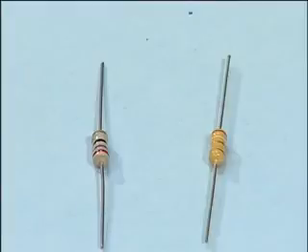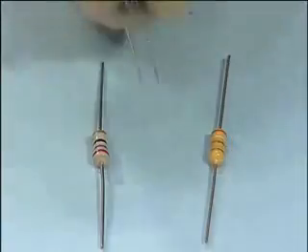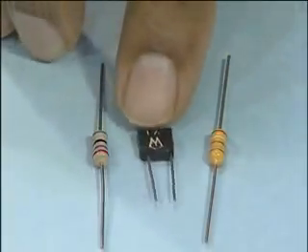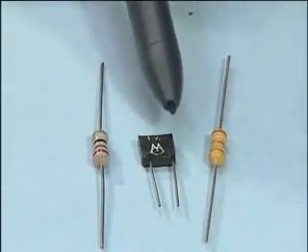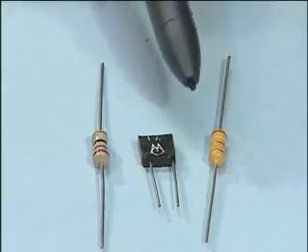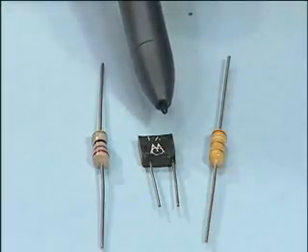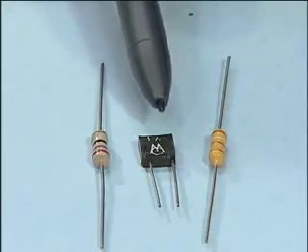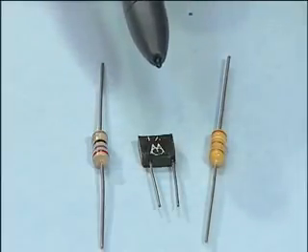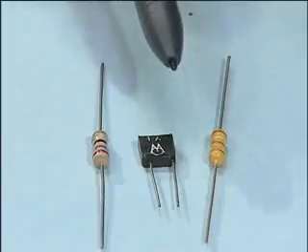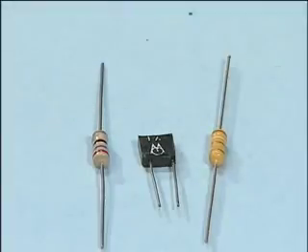I will put in a different type of resistor. You see this resistor here. This is a box type. This is made differently. This is called a metal film resistor. This is more precise than this one in terms of variation with respect to temperature and such, and they are generally used for frequency tuning components.